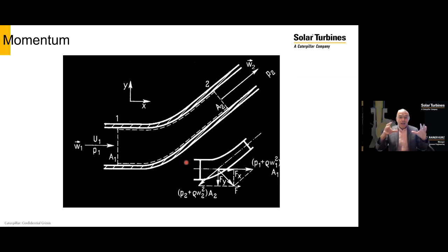So if I now have that pipe running in a rotating system, then I have a force times the distance, and that is work. So essentially, the general idea of energy transfer is that I force a gas from one direction into another direction. So that's basically what's happening in the impeller.